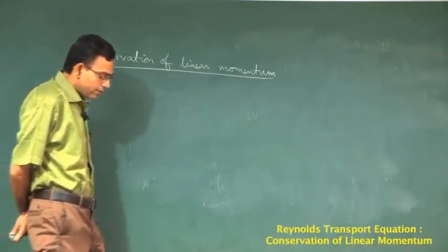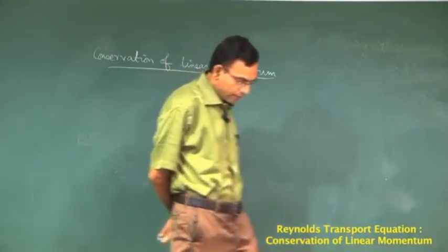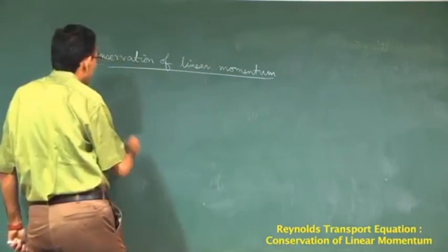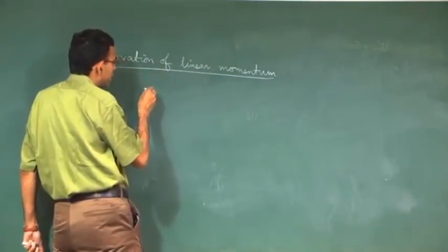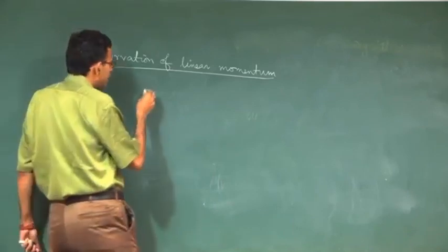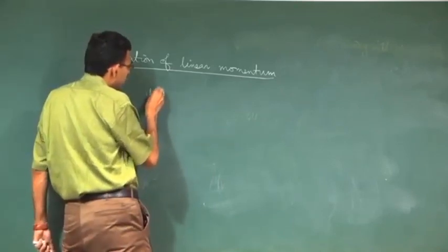Conservation of linear momentum will essentially talk about the Reynolds transport theorem applied for linear momentum. In that way, first we write the Reynolds transport theorem.